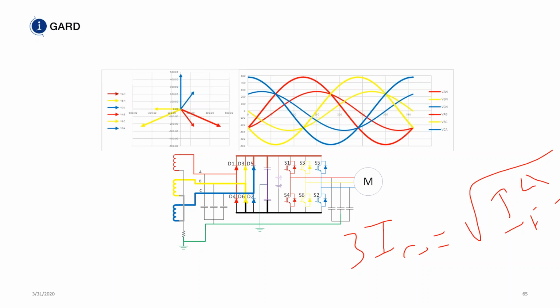From my understanding, it's going to be required on all resistance grounded systems. They don't limit it to portable devices, mobile devices, high resistance grounding, low resistance grounding. It's going to be required on everything as per the Canadian Electrical Code. It's been in the mining code for a long time, but now it's in all resistors.